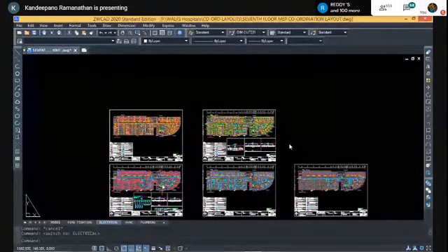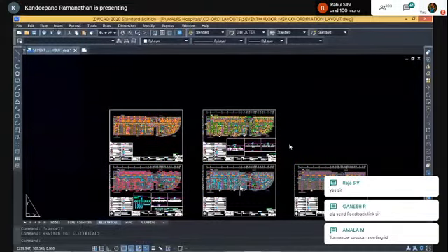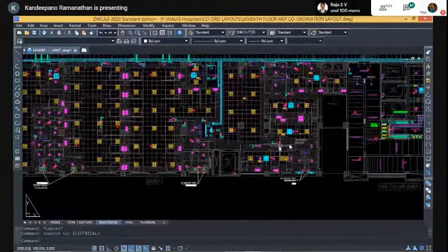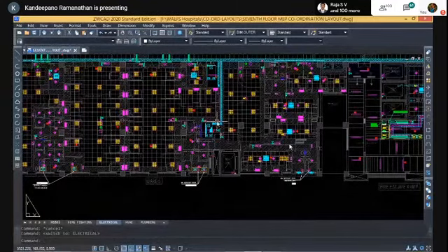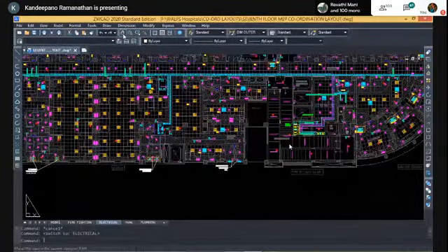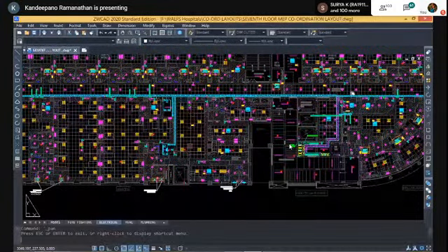Then this gives you the emergency lighting circuit drawing. This gives you the circuit layout. This gives you the switch control. This gives you the cable tray. So this is the cable tray layout, from one of the AHU rooms, the electrical room. This is the main electrical room. You can see the cable tray coming out. These will be above the false ceiling, and this is the central corridor. The cable tray runs in the central corridor and branches off to places where the power supply is required.